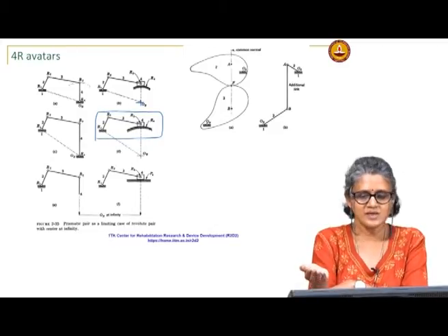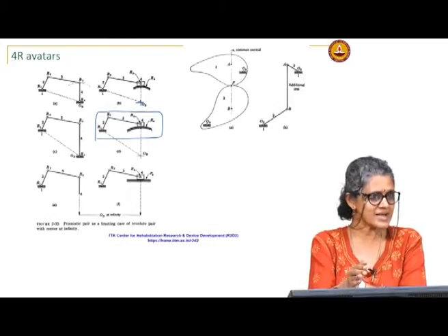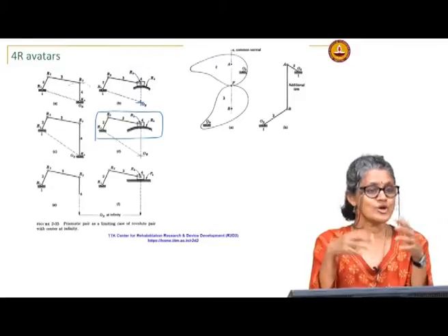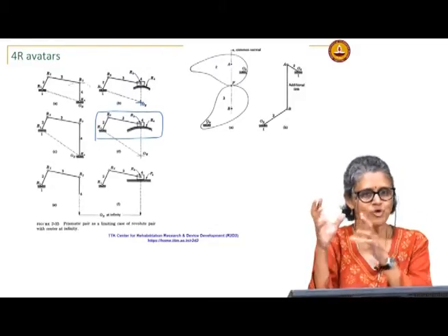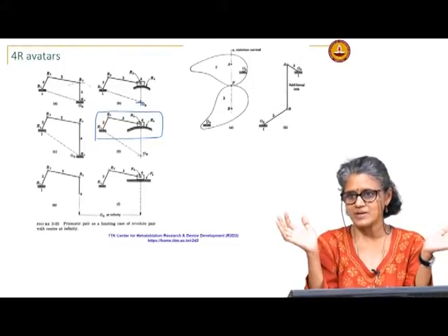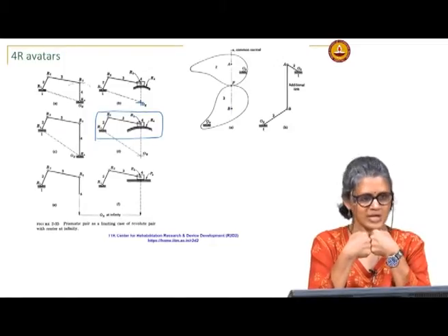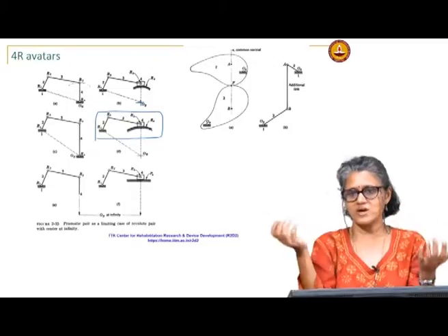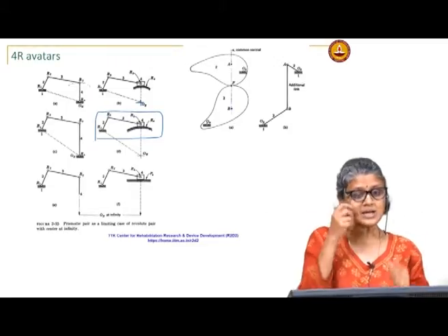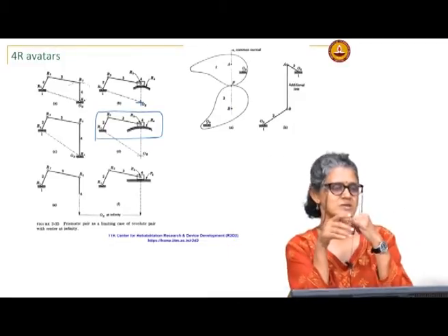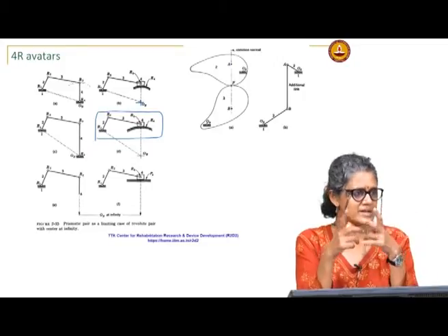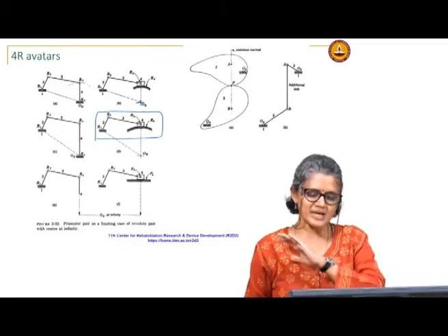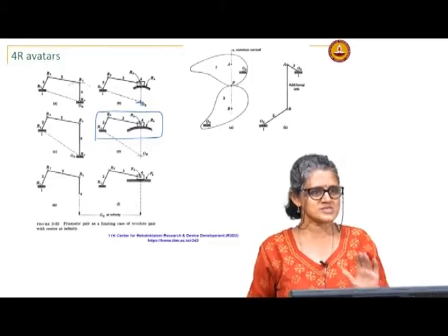The other side of the picture is what makes the cam follower system so versatile: it is essentially a series of changing 4 bars. With a 4 bar, once you have a set of links, what motion you get is what you get, right. With a cam follower system where the input and the output members are directly in contact, it is essentially a series of changing 4 bars, and therefore, you get a lot of flexibility in designing the input output motions. But cams of course have other problems, especially with respect to wear, maintaining contact between the links, etc. So, in some cases linkages are preferred, but of course again it depends on the application. That is the caveat everywhere, it always depends on the application.